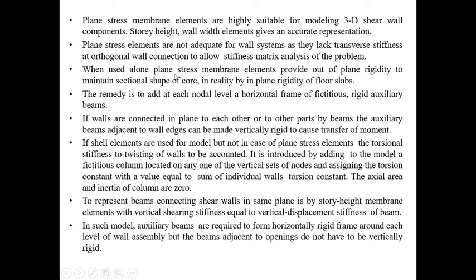So when using the plane stress membrane elements alone, they provide the out of plane rigidity to maintain the shape of the core, in reality, by the in plane rigidity of the floor slab. Due to that orthogonal wall connection, the lack of transverse stiffness affects the stiffness matrix analysis of the problem. To overcome this, at each nodal level, that is at each floor level, an imaginary rigid horizontal frame of auxiliary beams is provided.